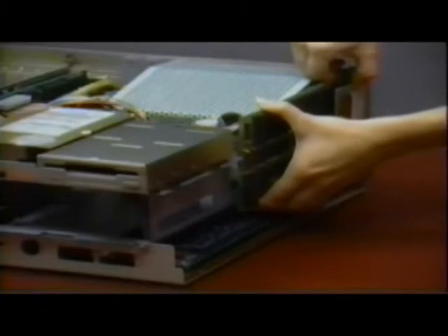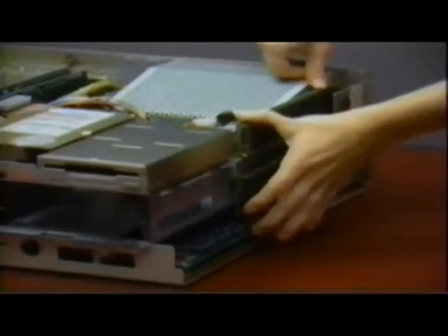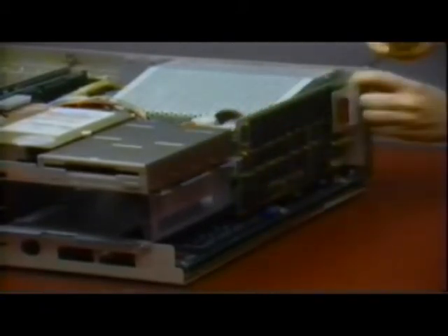The Flicker Fixer slides into the video slot beside the power supply. Remove the two screws securing the video slot cover and gently insert the Flicker Fixer, then tighten with the supplied screws. The Flicker Fixer outputs a higher frequency video signal than the standard Amiga video port, and therefore requires a multiscanning or VGA-compatible monitor. Here a Zenith flat screen is being used.